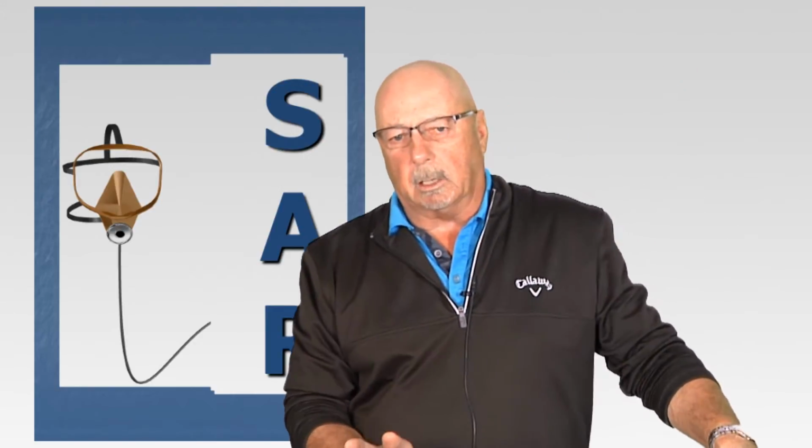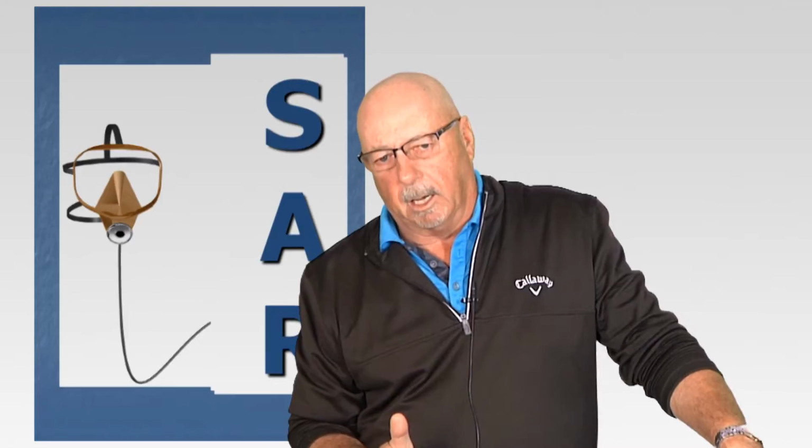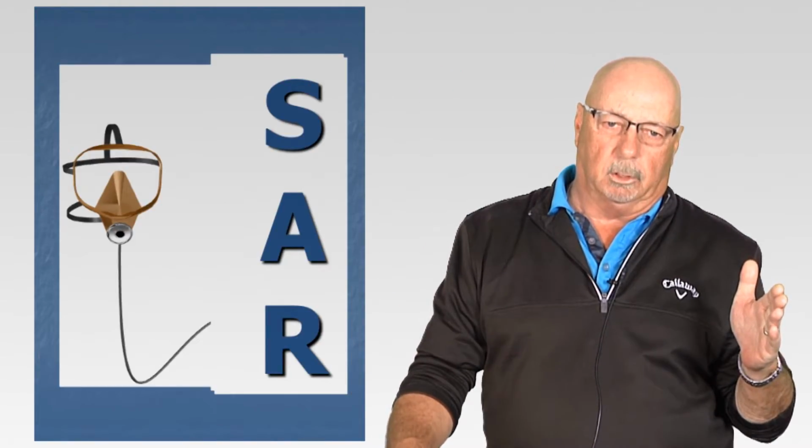Now, it's critically important that, number one, you place this air compressor in an area where it's going to draw in clean, fresh air. And OSHA requires that those generators have certain kinds of monitoring and filtering devices on them to ensure that the air that's being delivered to the user of this mask is clean.